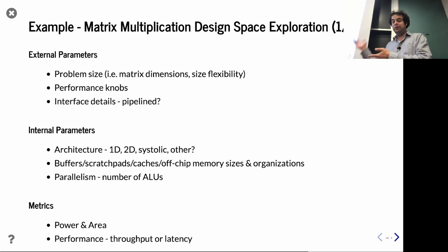For matrix multiplication, in addition to ALUs, you're very concerned about your various uses of memories, right? How you're using on-chip memories, using off-chip memories, how you're arranging and buffering stuff. There are a lot of choices there, and depending on how you design your accelerator, you have a lot of different knobs to turn. And then at the end of the day, what are your metrics, right? Here I've mentioned PPA as the one. We talked about this 5 slides ago. There are like 10 metrics, right?